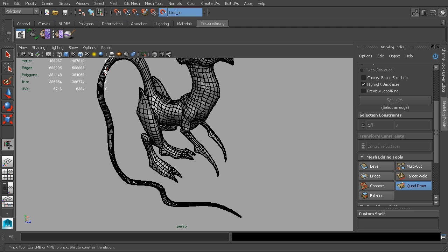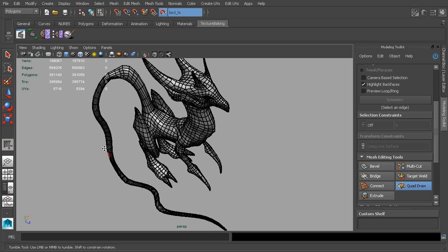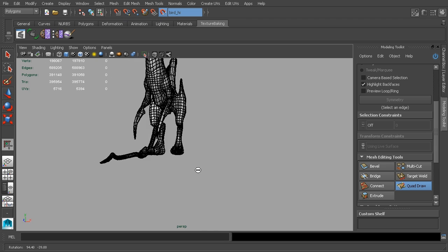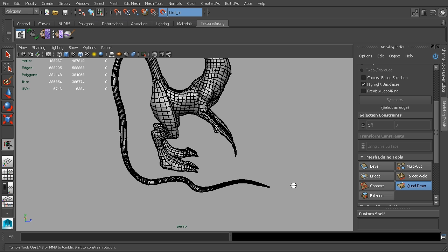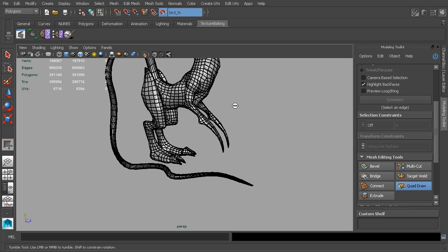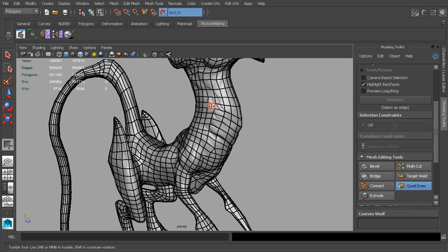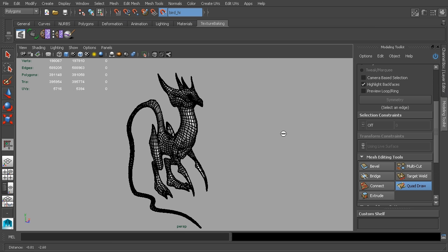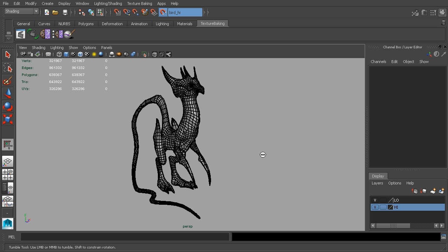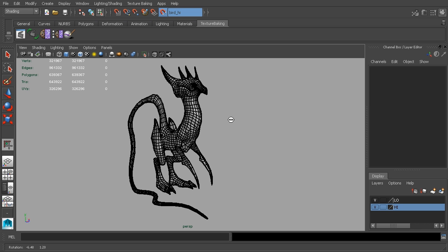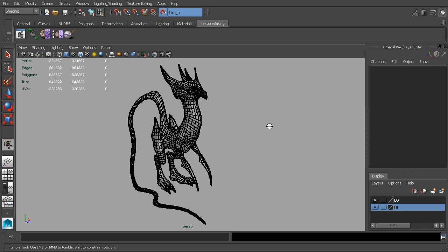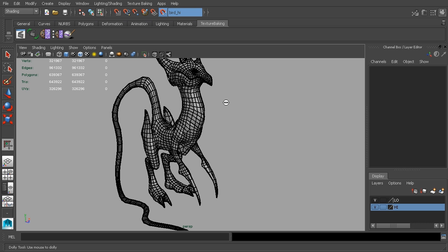Now in this case, because it was asymmetrical and because it had this sort of curve in it, using a NURBS curve with an extrude made some sense. But you could build your geometry any way that you want to, and then do the shrink wrap, and that basically takes that topology and kind of smooshes it onto the high res mesh so that the shape matches up. Well, now that we have our high res and then we have a low res that matches up and is the resolution that we want, the next thing that we want to do is bake out maps.